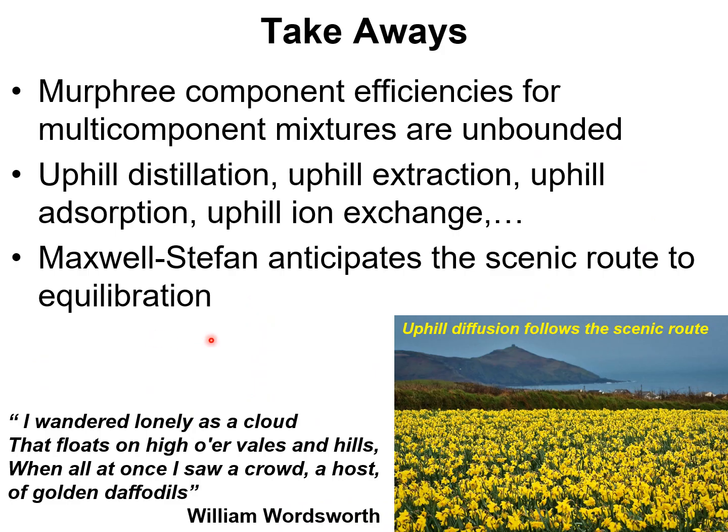There are three takeaways from this presentation. Firstly, Murphree component efficiencies for multi-component mixtures are unbounded. They may have values exceeding unity or lower than 0. We've analyzed multi-component distillation, multi-component extraction, and mixture adsorption in zeolites. In each of the examples we have considered, we have the possibility of uphill transport and component efficiencies exceeding unity.